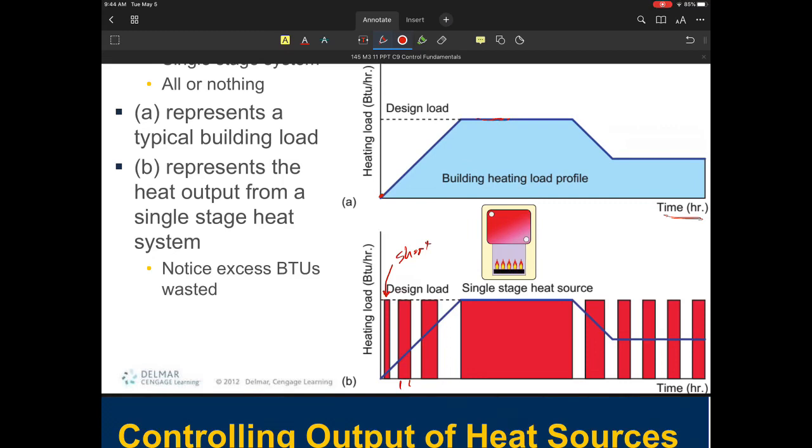When there's very little load, the boiler will heat up and put a bunch of energy into warming up the boiler system and the mass of the piping in your system, and with a little tiny bit of a lag, it's putting all this energy in there, but it doesn't really need all of it. It doesn't need 100% of that. So it basically heats up and shuts off. Oftentimes with those, you typically get more temperature swings in a system than you would at a full capacity load.